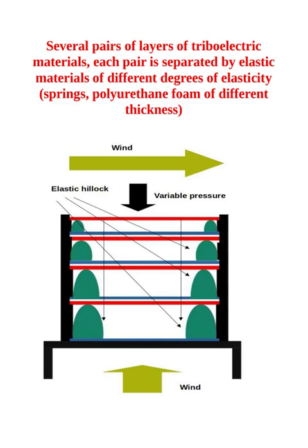The device is a sandwich consisting of several layers. Materials that make up triboelectric pairs, as well as materials used as a conductive medium, are used as layers. A bumpy, elastic material is located between the materials that make up the triboelectric pair. In each layer, the height of the mounts defined for this layer will be used.